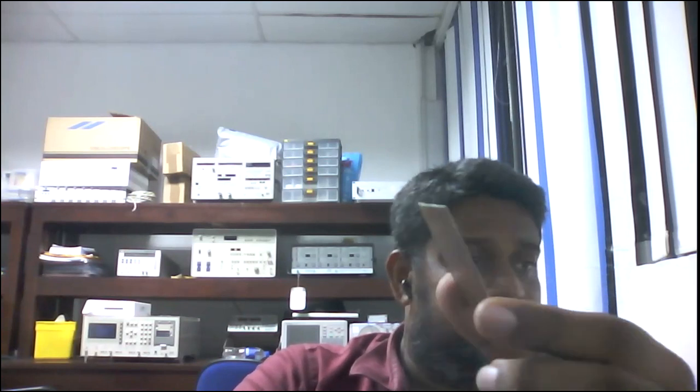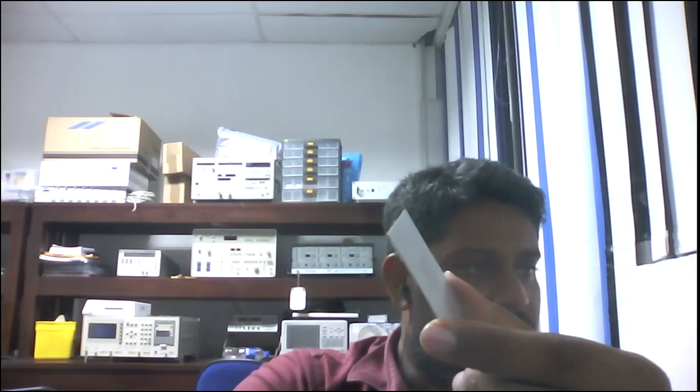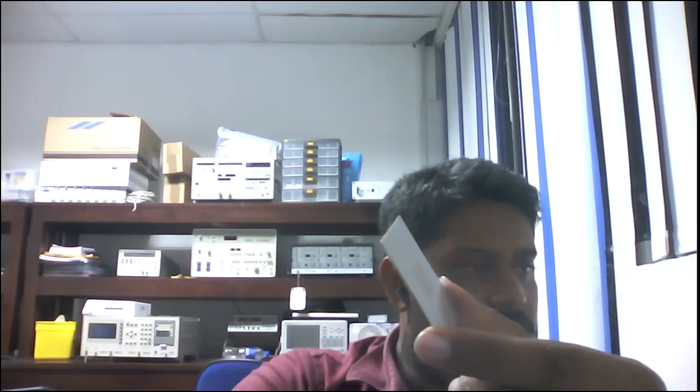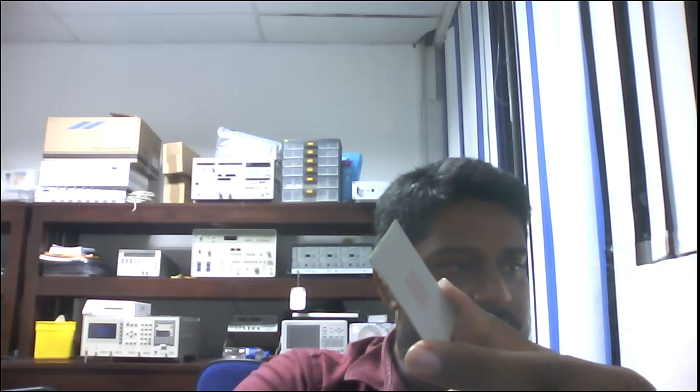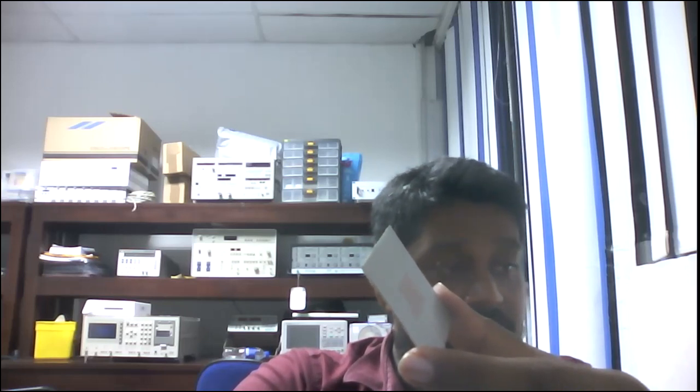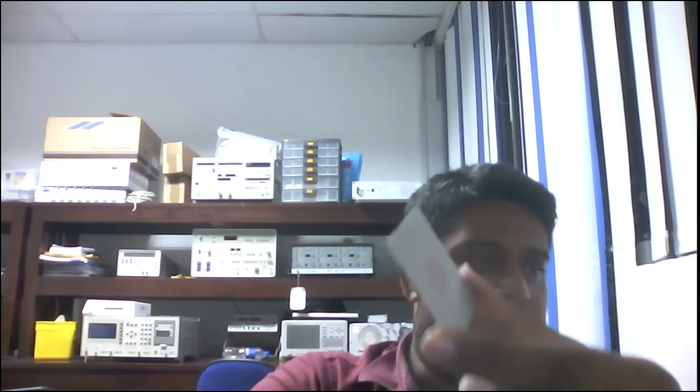This is actually a microstrip. So it is like this: we have insulation material here, and here we have a copper coated plate, and here also a copper coated plate. These are copper, and this is insulation material. There are many types of microstrip boards available: FR4, Neltec, Rogers, likewise. FR4 is not good for high frequency, maybe a maximum up to 2 gigahertz is okay. These are called substrates; these are high speed substrates.